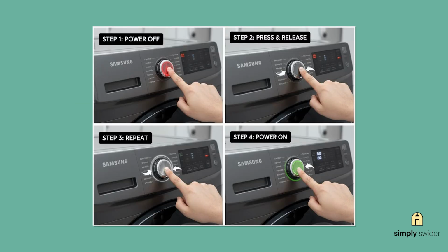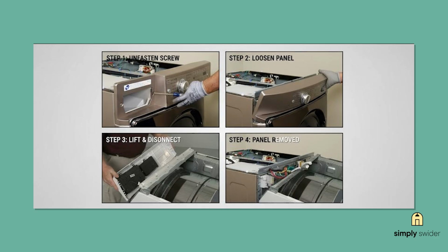Here's the fix. Power off the dryer completely, then go through and press every single button on the control panel one by one. Sometimes a button gets stuck from spilled detergent or just general wear and tear. Press each one firmly and make sure it clicks and releases properly. If you find a button that feels mushy or doesn't spring back, that's your culprit. Unfortunately, if the buttons look fine but you're still getting the error, the user interface panel itself is probably failing.